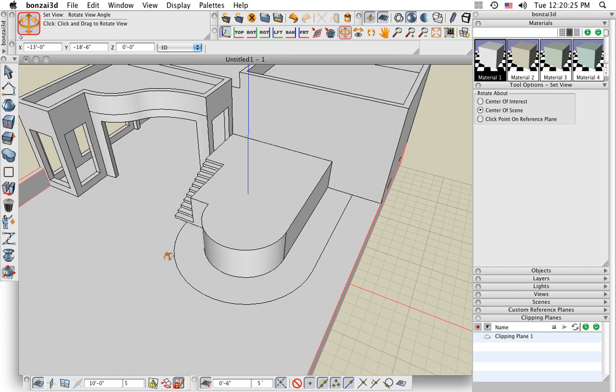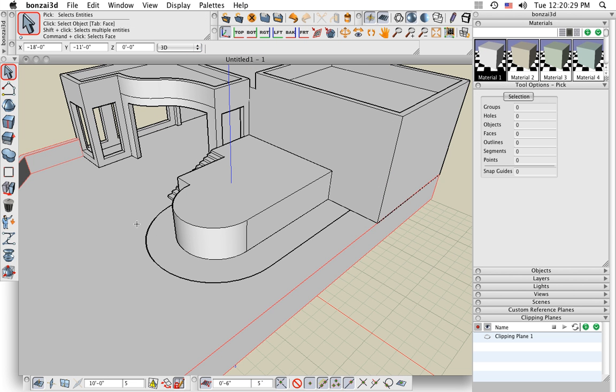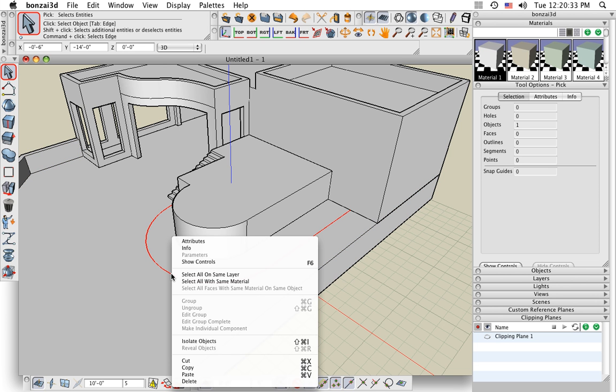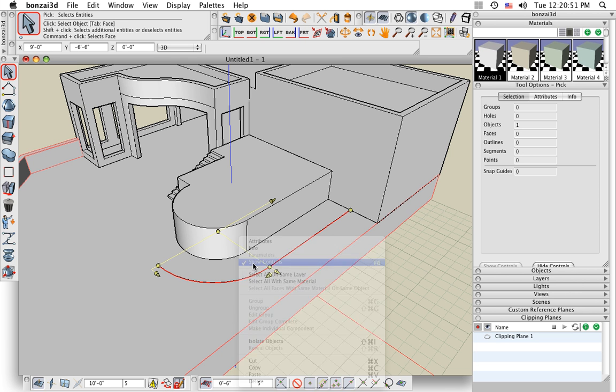like that. And these controls that you saw earlier in the orange objects actually can be recalled at any point of time. So if an object has controls, simply click on the Show Controls menu item as you pick the object, and it will give you whatever controls are applicable. In this case, I can change the angle of the arc, for example. I only want a 90-degree curve over here. And when you're done working with the controls, just turn them back off.